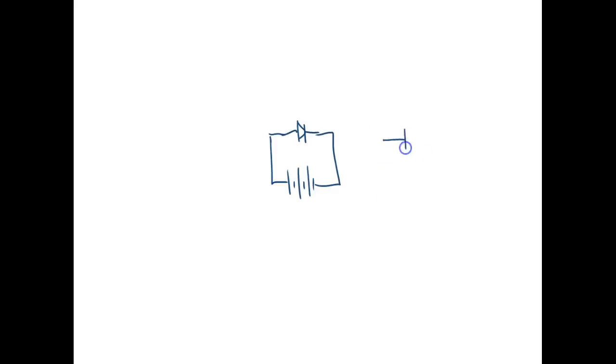Well, we would have to do what any normal person might. We'd have to put a resistor in here somewhere, right? In series. Now we're okay. I'd have to size that resistor for the current, but now it's forward biased, and if this was 12 volts, this resistor would drop approximately 11.3 volts, and this guy right here would drop about 0.7.